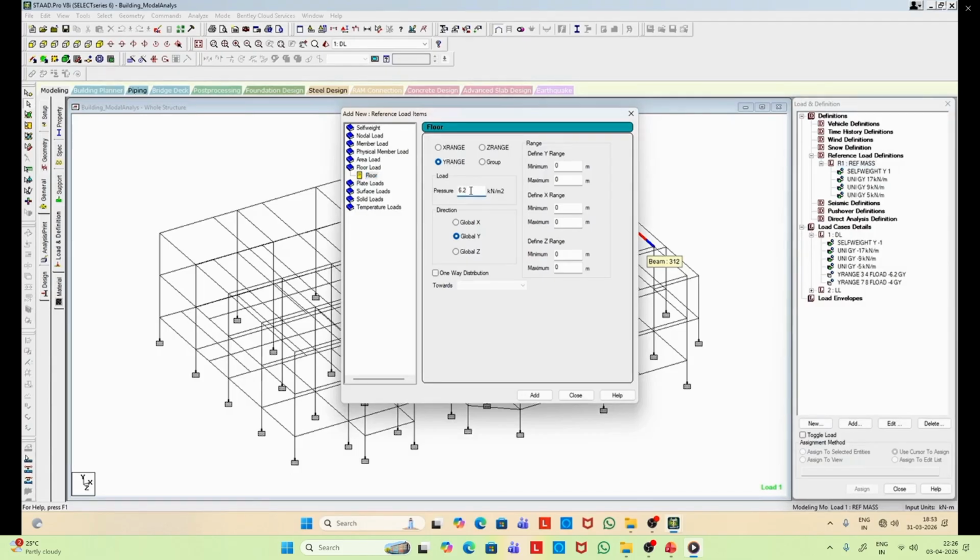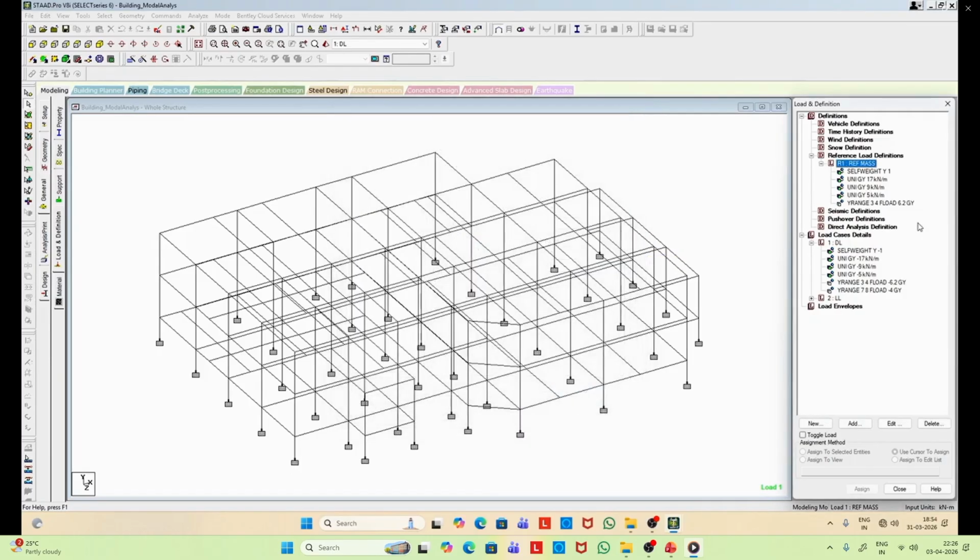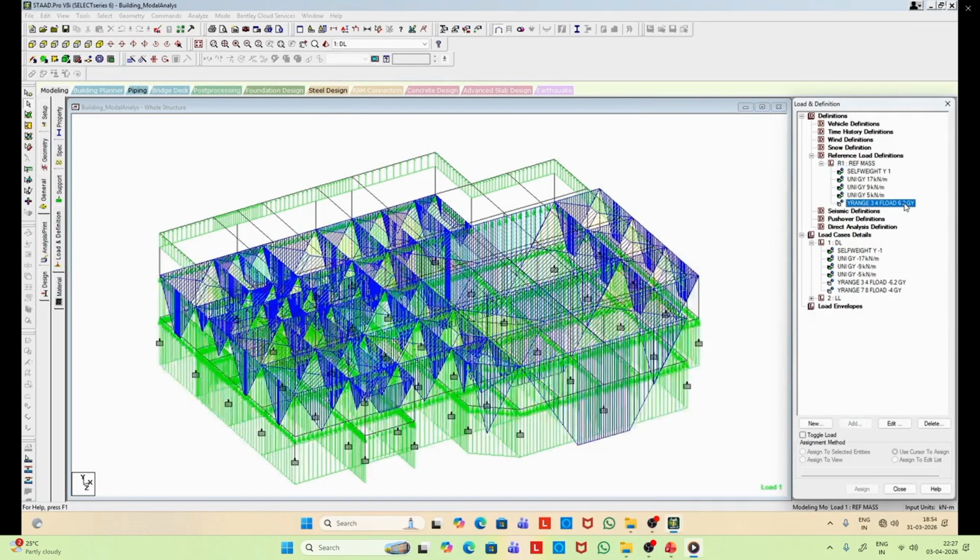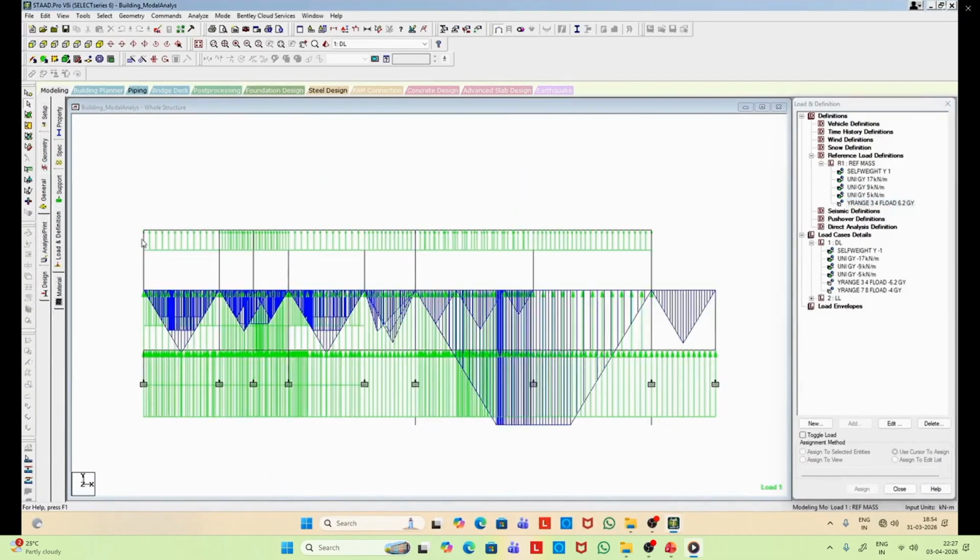Recall there were walls on major beam and minor beam. Now we apply the floor mass. Okay. The same way, we first copy it, and the same way we apply, and it is now applied. So we have to repeat for the other floor. You can see one floor it is applied.